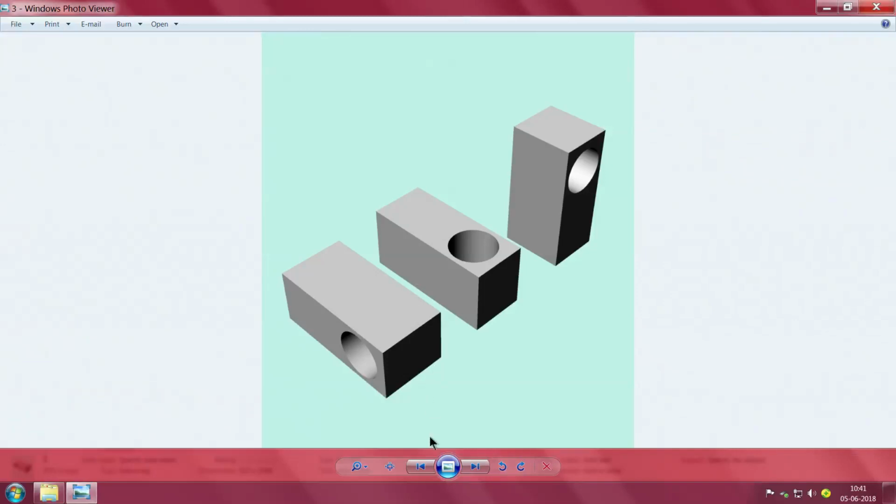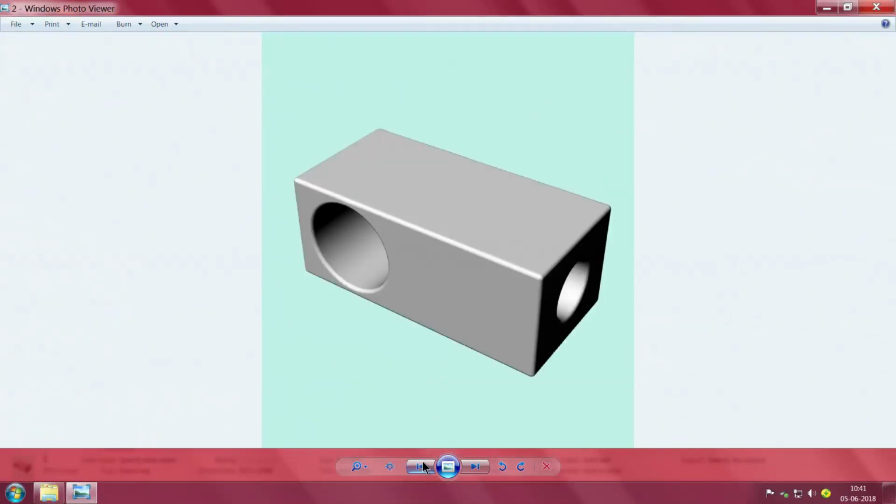If you kindly remember the previous thing, you see here I have a bore. Now if I keep it flat and try to build, as the software checks first, a little bit of build material or support material is built here. Same thing here, support material is accumulated.